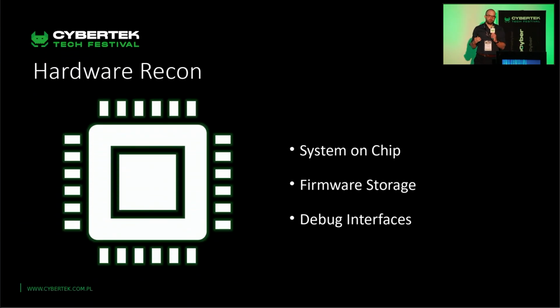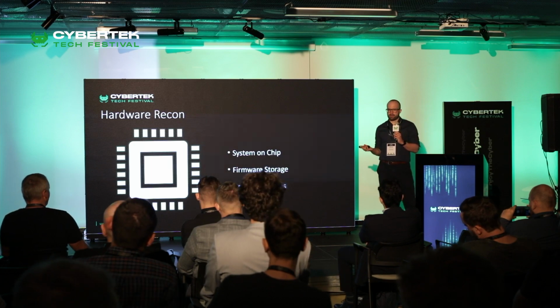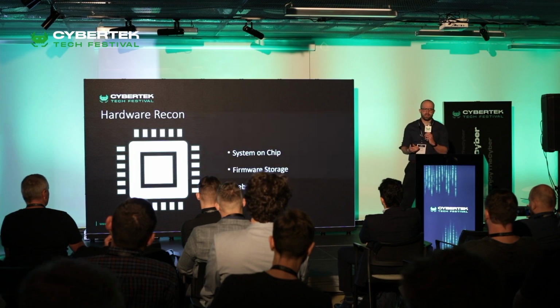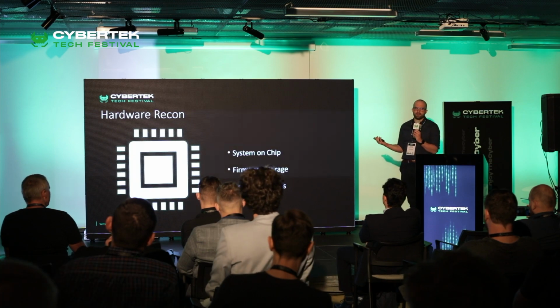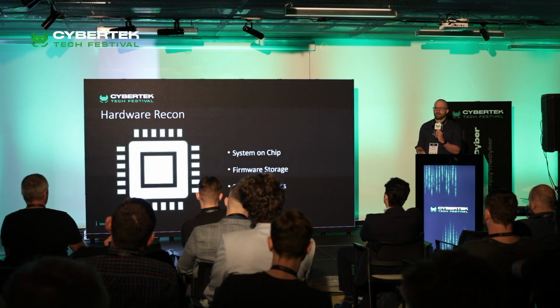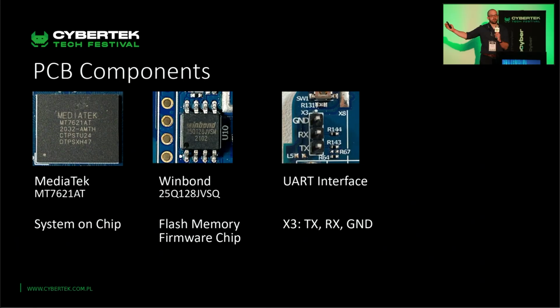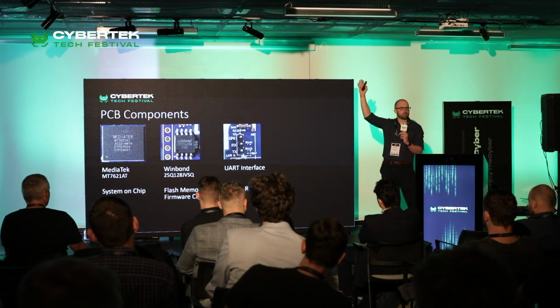First, when we open up a device, we look at the components. What's the system on chip? Where's the firmware stored? And are there any debug interfaces? And if we open up this device, we find a MediaTek system on chip. The firmware is stored on a WinBond flash memory firmware chip. And we find a debugging interface that, if you're familiar with hardware interfaces, who's familiar with hardware interfaces?